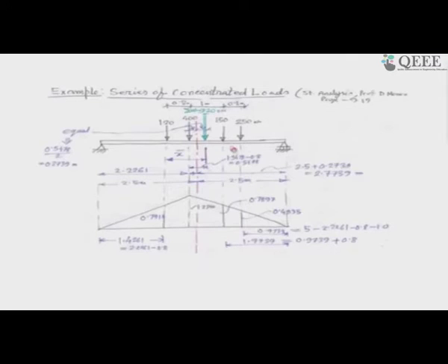So, this is where it is located. If it is located there, you see that I have found out that this is the location x dash, and I have located where the resultant should pass through. So, this is the geometric center line, and from the geometric center line you can now have the computation, everything ready.